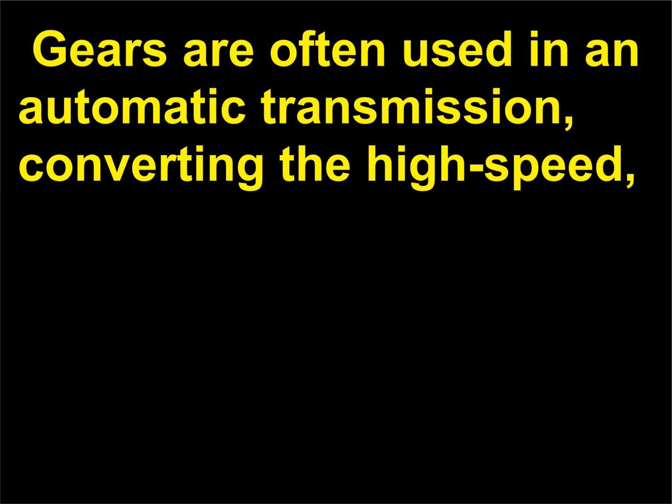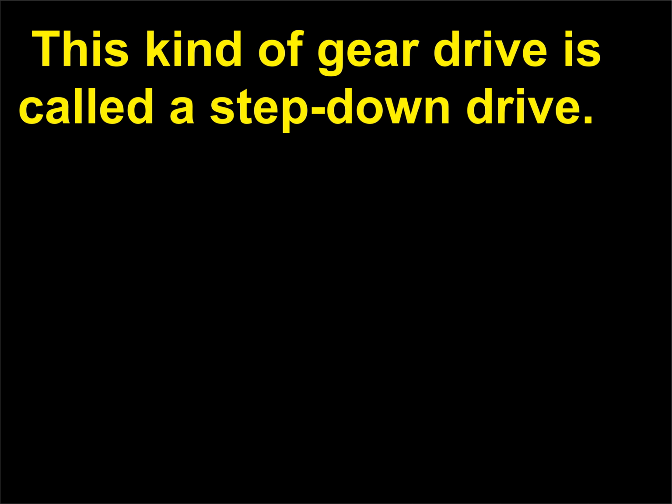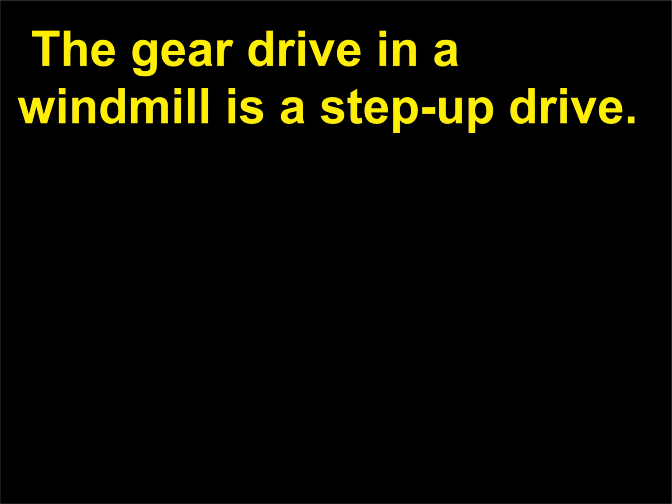Gears are often used in an automatic transmission, converting the high speed, small torque output of the engine to the low speed, large torque output needed to turn the wheels. This kind of gear drive is called a step-down drive. On the other hand, in a windmill, the blades turn at a low speed but provide a large amount of torque. The gear drive in a windmill is a step-up drive.